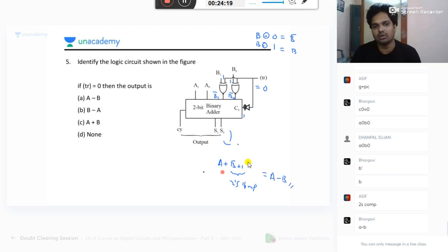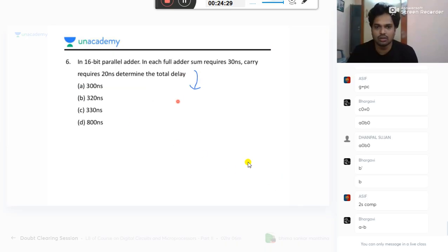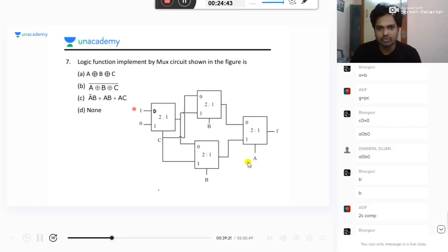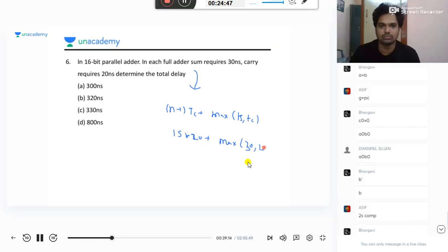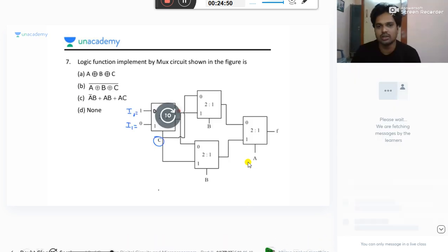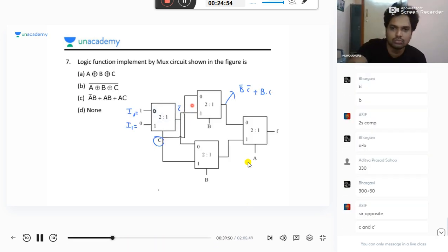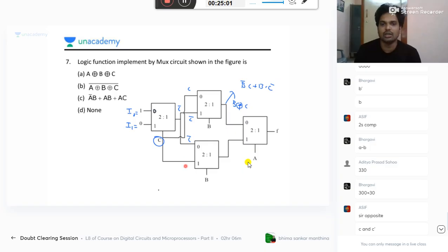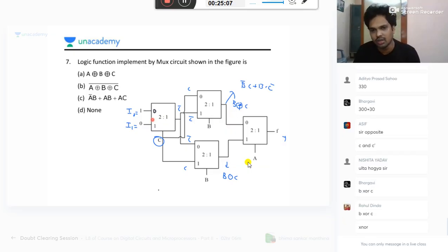Okay, so here, what is the question? First, he has given this, and it is an SR NOR latch. So first question, first option A, Vi is equal to 2. Then Vi equal to minus 1. Vi is equal to minus 2. So here you take this as S and R. What is S in that case? Minus 2 is more negative than minus 1, so S equal to 1. R equal to minus 2 means 0. So what is your P? It is 1.